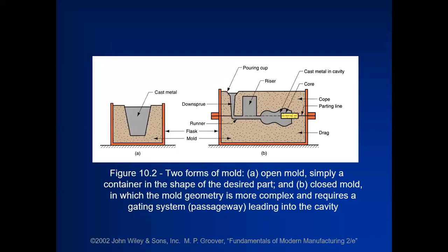Sir, does the riser let the gases out? No. The purpose of the riser is that it stores the metal during the solidification process. As during the solidification process the metal solidifies in the cavity, as the metal solidifies, the volume of the metal shrinks.